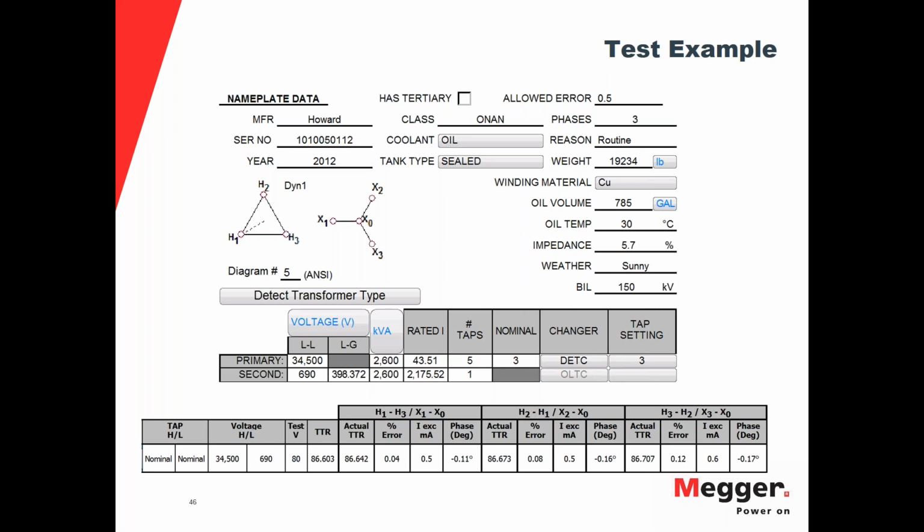That's acceptable. There's nothing in the standards that I'm aware of that tells you there is a set point for how much deviation you should allow for. But obviously, if you had a high deviation percentage or degree, then you would know that there's an issue, which will allow you to do further troubleshooting and diagnostics. And again, if you were to connect it up completely backwards and do the test, you would have 180 degrees out. This would highlight red, and you'd be able to say, okay, yeah, there's an issue here.